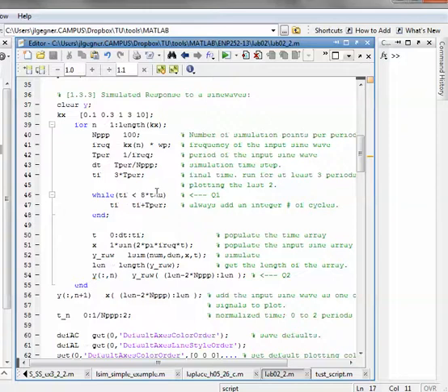Boston can guide you on this, but pick values that will generate time domain sinusoidal responses at frequencies below the corner frequency of the filter and above the corner frequency of the filter. And I would say one that's right at the corner frequency. If you remember, the filter that you designed or built actually had a little bit of peaking right at the corner frequency. So it would be nice when you generate these plots that you would show